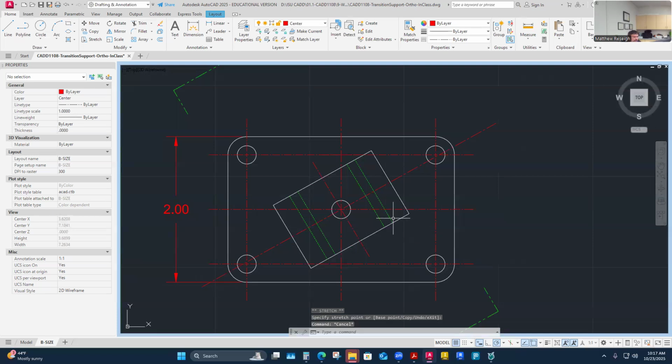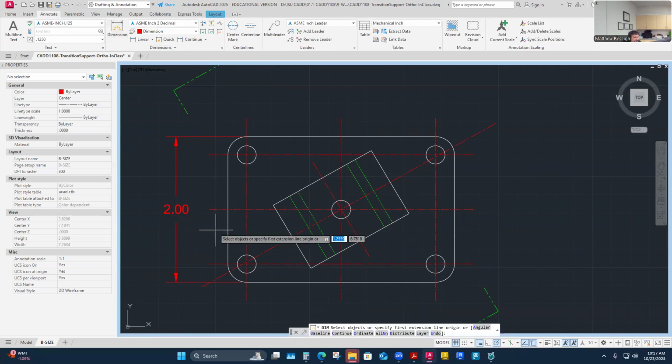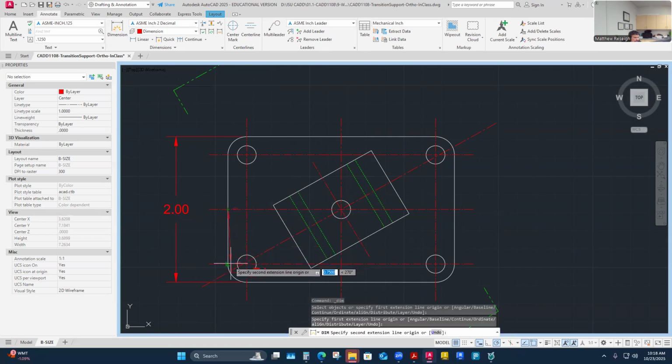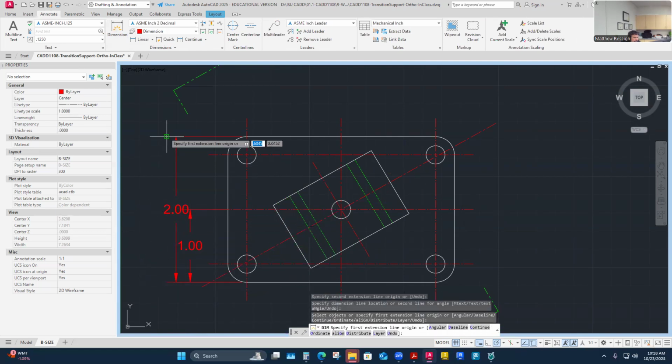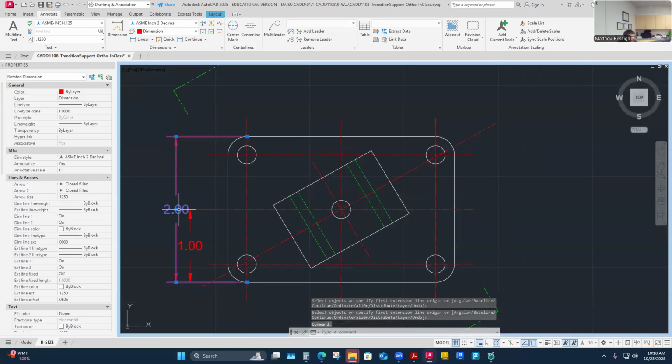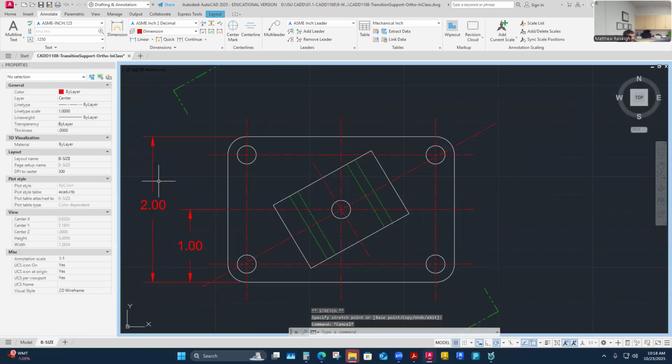And one of my dimensions, I'm already planning ahead, so that's me thinking about this part. But let me go back to just the base part, and start to think, well, this 2 inch, maybe I'll control it from a center too. So I'm going to control center and center. So let me dimension this. I'm going to say that 2 inch actually is going to come from center. I'm going to say that it's 1 inch out and then it's 2 inch. So here's my maze. Now I'm coming off a center line control. 1 over from control, back 2 to the back surface. Okay.